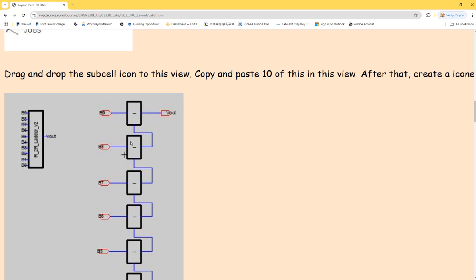I know the 3 resistor module works past the DRC. I reuse it, and I just use physical wires to make the connections. I know the physical wires are very unlikely having any issues. And I know these 3 resistor string modules are working, so I put them together, I connect them with the wires, so I know it's going to work. I make the connections, I do a DRC, boom, it works. DRC error clean. And then I generate another module out of it, so I know this is a DAC chip that I can use for millions of times. I know everything works inside.